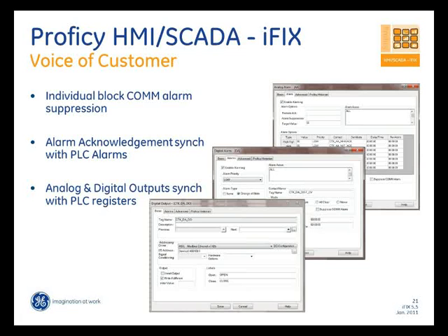So that has led to a change in behavior of our analog and our digital output. There is a checkbox that we have introduced in analog and digital output that prevents the AO and the DO to write out in case the block is reset, which means if you reload the database or iFix starts over, you can prevent the analog and digital outputs to write out to the PLC and force a read first to make sure that they are synchronized. So that's something that we've added to AOs and DOs.